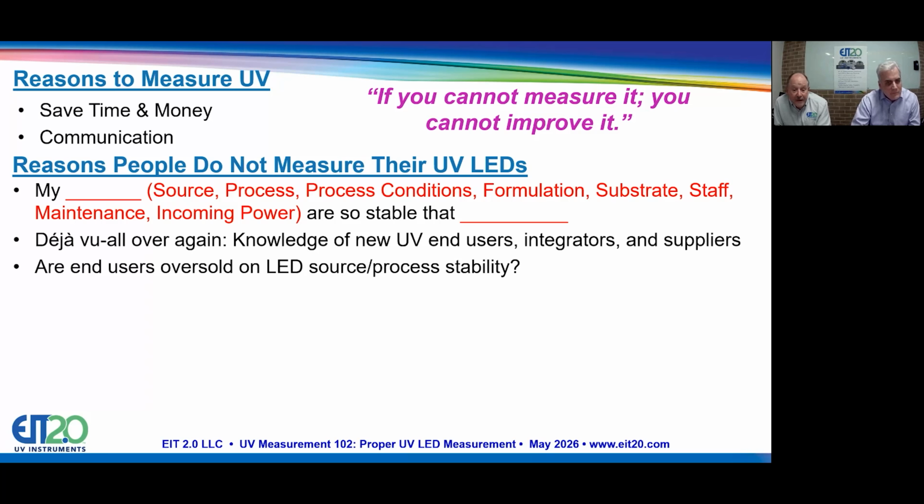If I were to pick on some of the source suppliers, and not all of them, I think there are a few that say, hey, our LED is a solid state device. It's so stable that you don't have to measure it. But there's a whole bunch of other things that go on in the process that you have to track in order to get good cure.